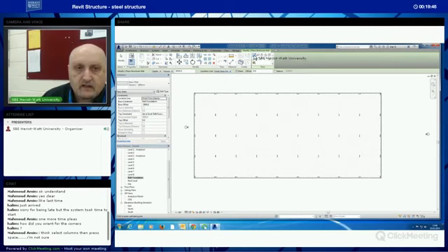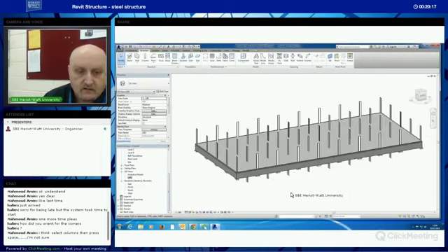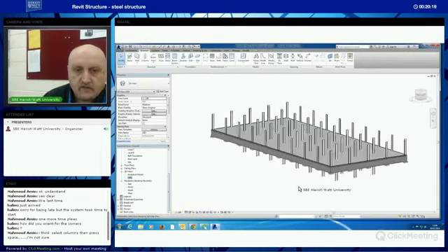and then here I can either use this line tool and select it corner from corner all the way round, or I can use this line selector, and that's what I'm going to use this time, because the last time I remember I used this. So I'm going to select the line tool, and I'm just going to select the lines. And then make sure I select the outside of the lines. That's fine. I'm going to check this in 3D again, and you'll see I now have the walls in.